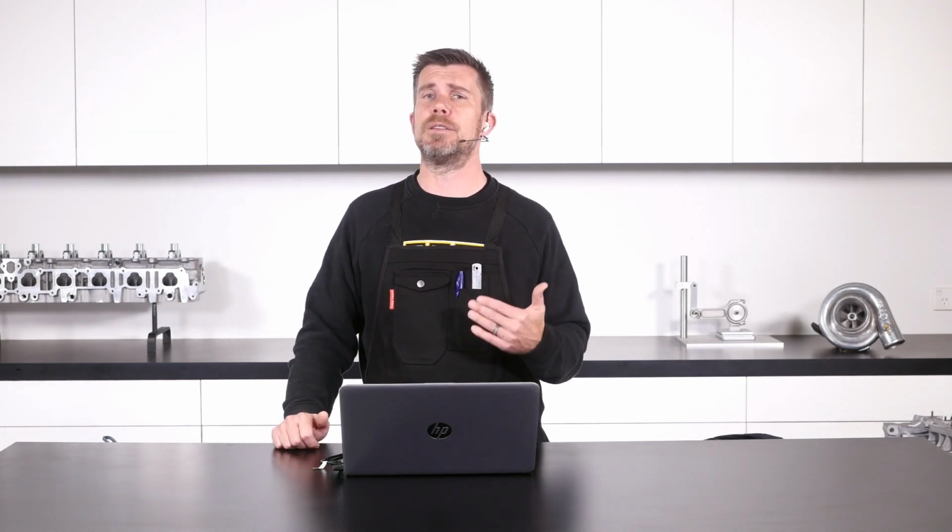To give you a rough guideline of where we'd expect those numbers to be though, at high-end drag racing, if we can, we'd like our exhaust manifold back pressure to be below our inlet manifold pressure. Then for circuit racing, where we still want relatively good response, our ratio is probably going to be somewhere in the region of 1.0 to maybe 1.5 with our EMAP above our IMAP. And then of course, if you want really good low RPM response with your turbocharger, you might drive that turbocharger a little bit harder with a slightly more restrictive exhaust side, and that's where you might be stepping up to around about double the inlet manifold pressure.